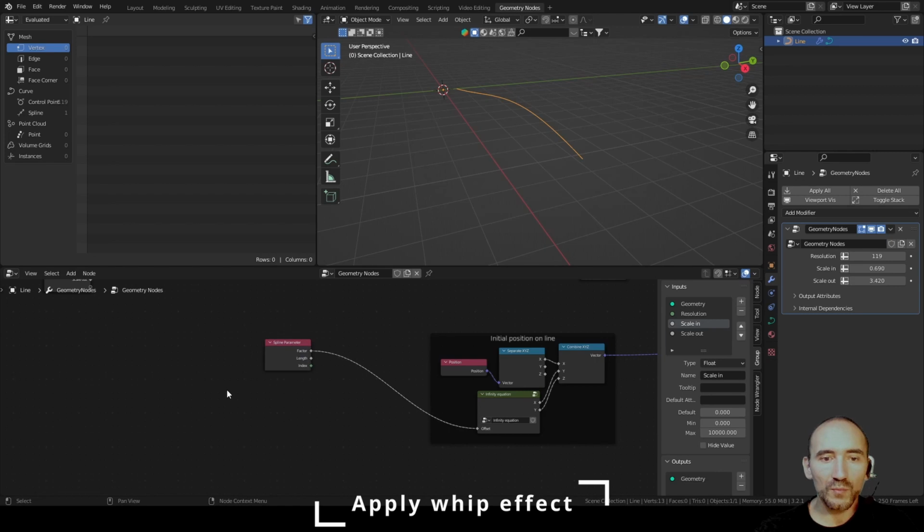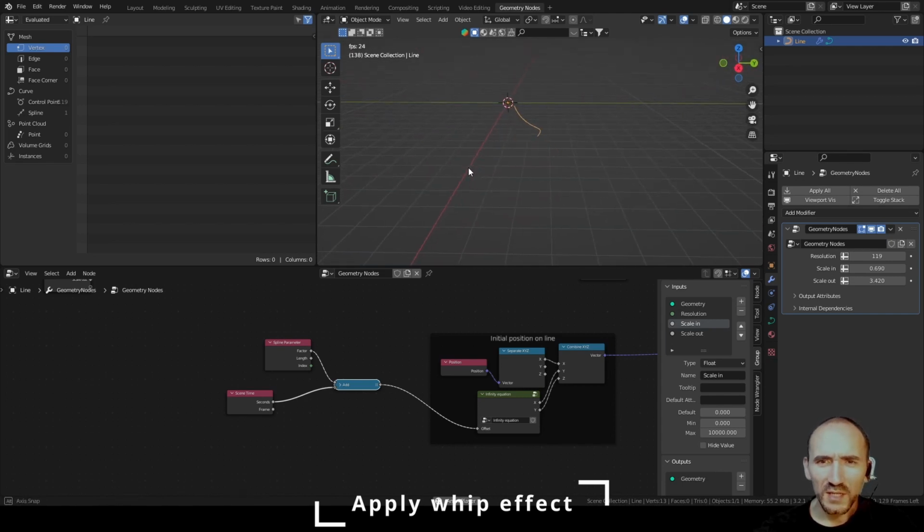But how can I see this in an animation? I have to play with the time information, so we can add with Shift Ctrl right button drag these to add the seconds animation to the factor, and if I play the animation we have this movement. This is the opposite movement. We want this point to go first, these points.